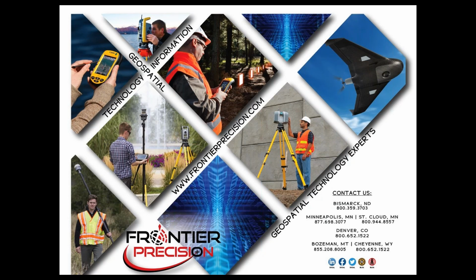I just want to note too that this process is definitely recommended for when using a 3D road and cross sections. If you're not using a 3D road or cross sections for stakeout, then the traditional method is probably still going to be used, because without those cross sections, you don't have strings.